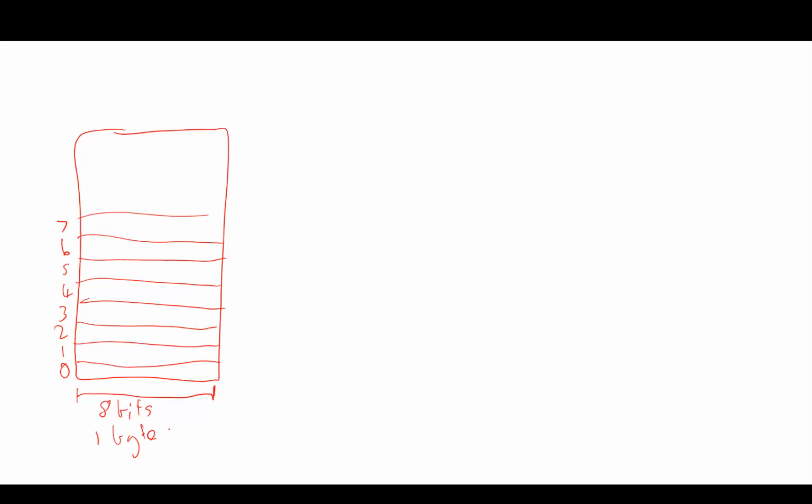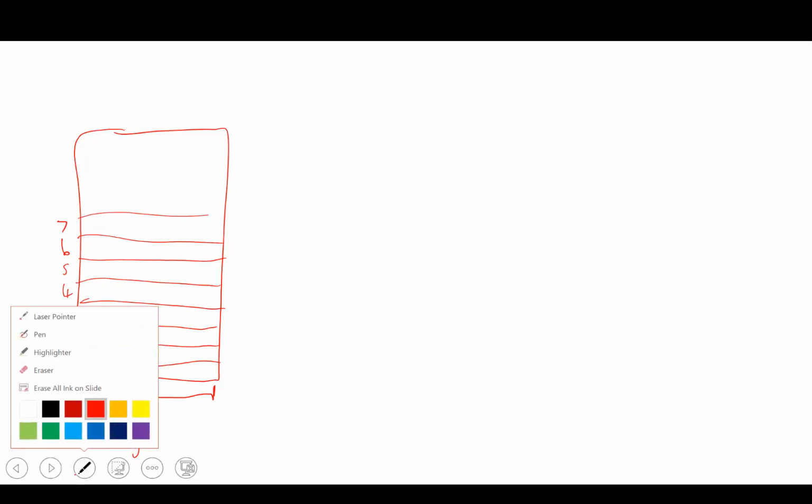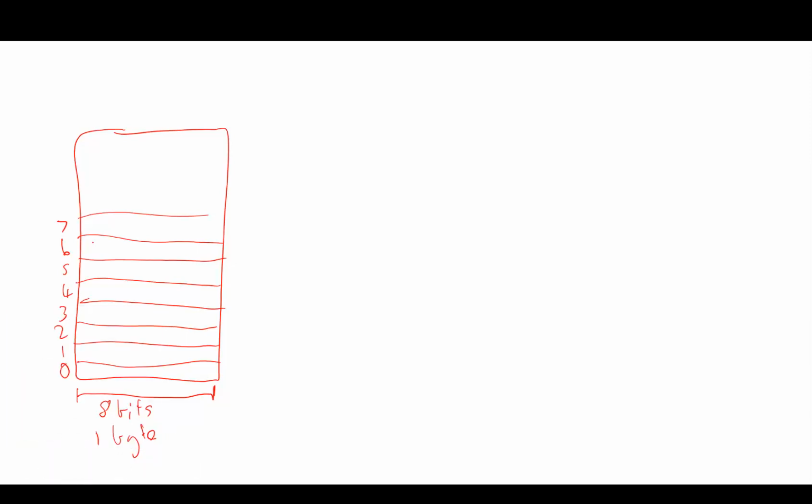So if you wanted to write to a particular byte, let's say this one here, you did a store byte to there, what you would see on your Avalon bus address value would be the address of that byte in terms of the half word alignment.